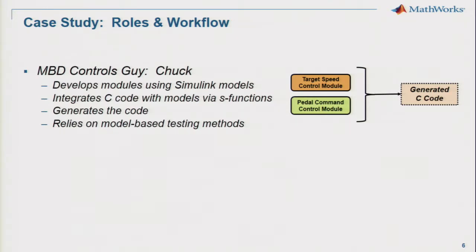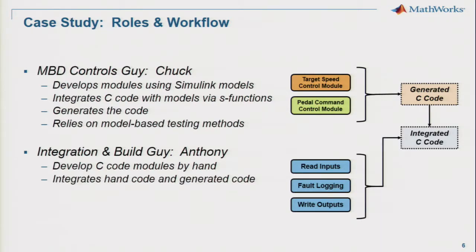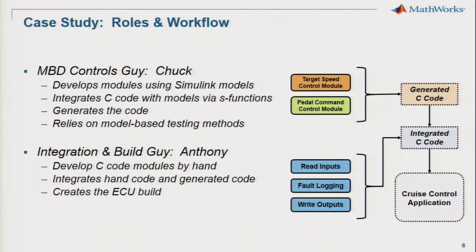Okay, thanks, Chuck. Yes, my role in this will be I am the integrated and the build guy, where I develop C code to read and write IOs, and for fault logging purposes also to log the fault into non-volatile memory. I also integrate the hand code with the auto-generated code that Chuck delivered to me. Yep. I also create the final ECU build for the cruise control application. And finally, I rely on my test on the HIL bench.